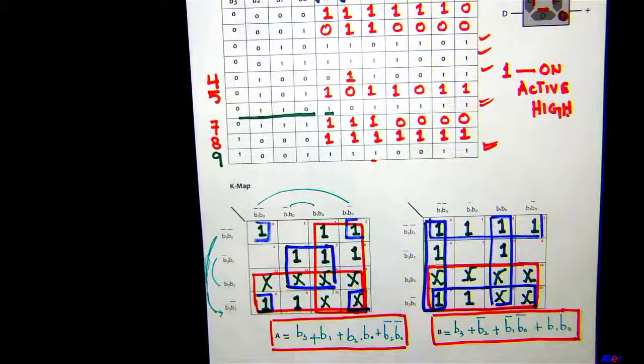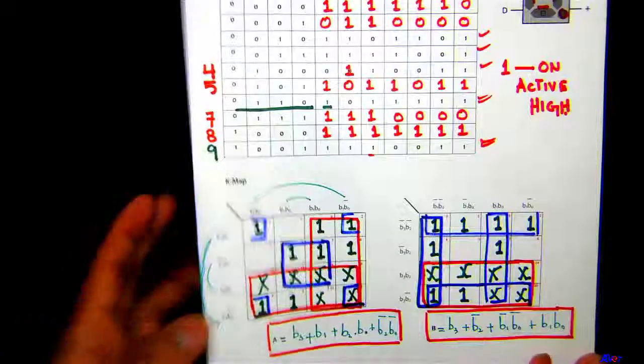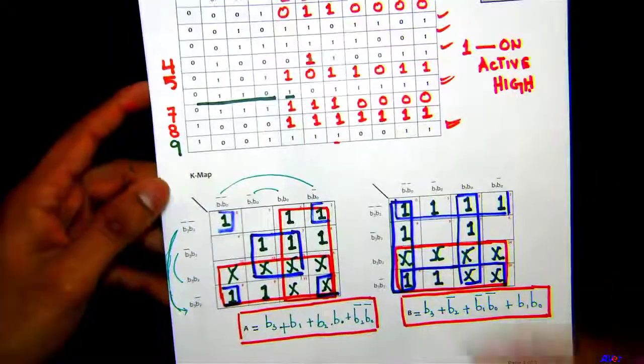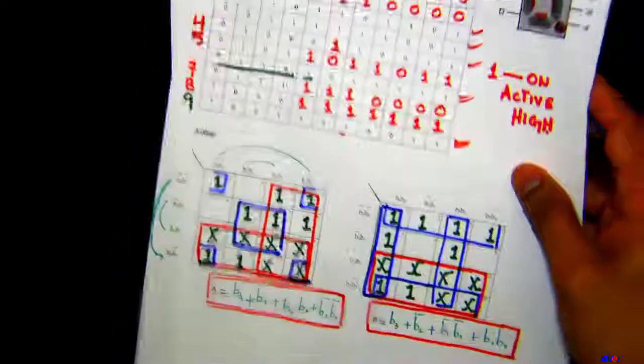Okay. Remember, you're going to have to do this for A, B, C, D, E, F, G for the pre-lab, but you can use Logisim. The tutorial that I made for you just runs through how to derive a logic expression for all the segments from A to G using Logisim. So that will be a faster way of doing it. You don't have to do it by hand, but I just wanted to do at least 2 of them. Okay, all right. Let's move to the implementation part.